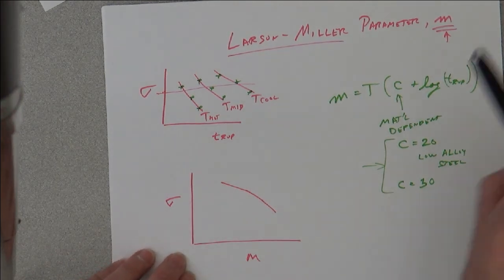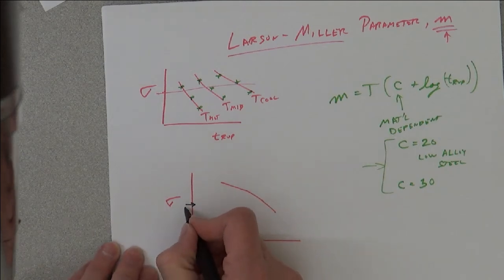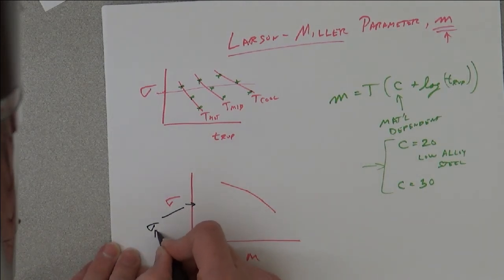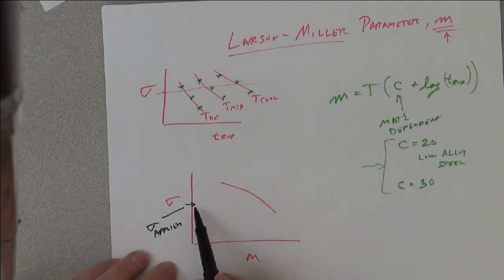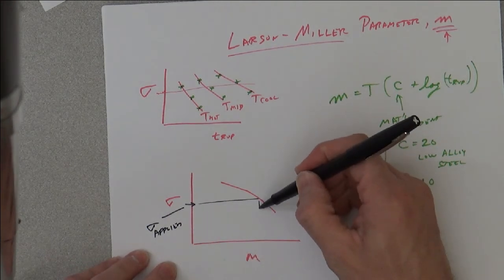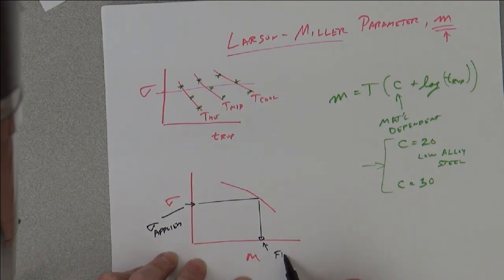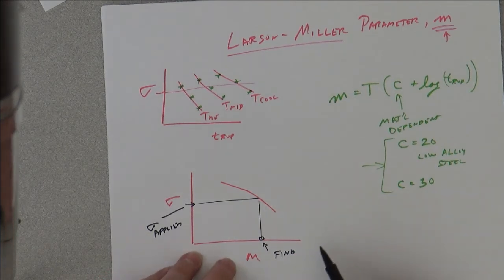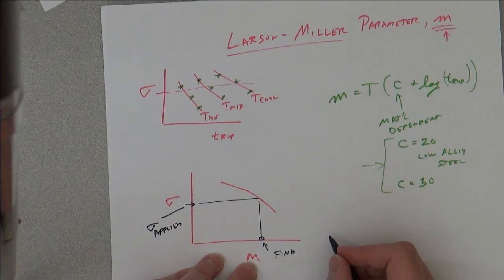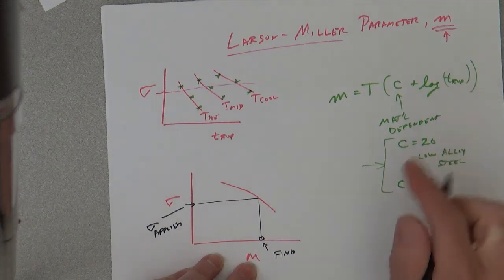If you know the applied stress, you can read your Larson-Miller parameter and then use that to get the rupture time.